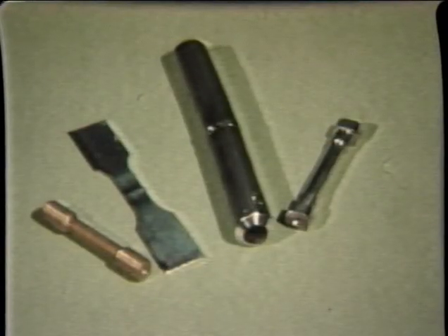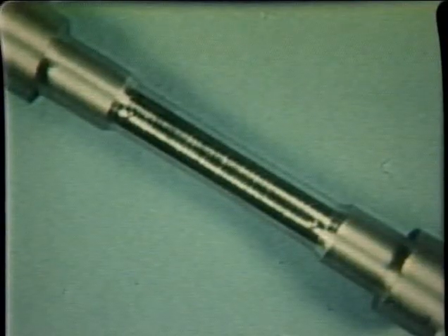There are a variety of tensile tests, differing primarily in the specimen's shape and location of removal. All weld metal and all base metal specimens are used to determine the strength and ductility properties of each. These tests are commonly used to classify base and weld metals to national standards.